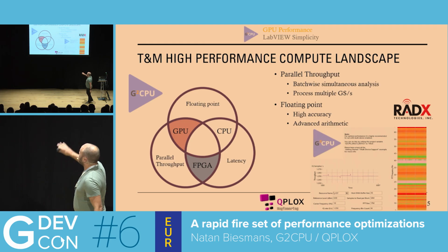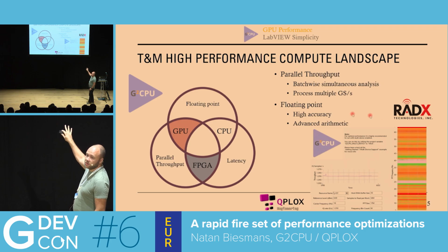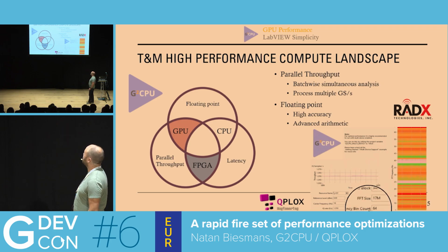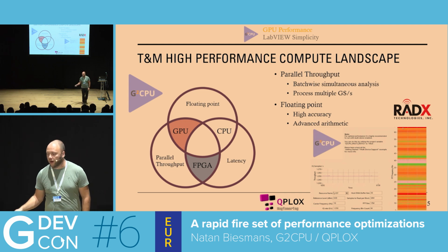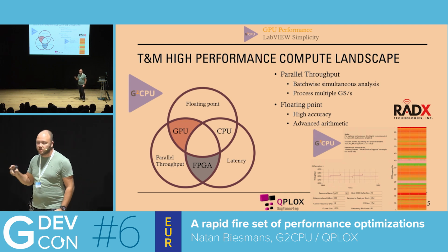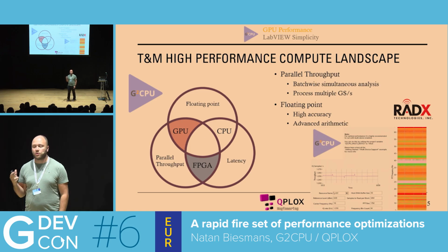As a quick example of how that looks, this is an example of the toolkit where we're streaming from a VST at the full 1 gigahertz on a PXI and doing a 16 million point FFT. Doing a full analysis on the go for hours on end without any issue. This is what the GPU is absolutely great at.